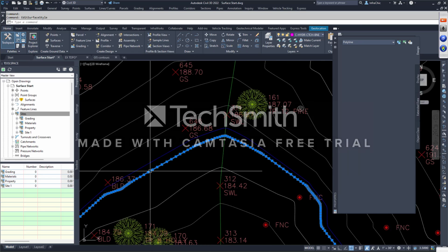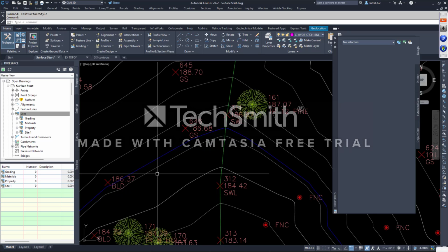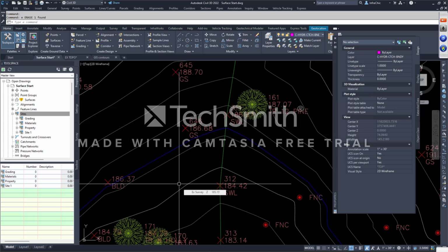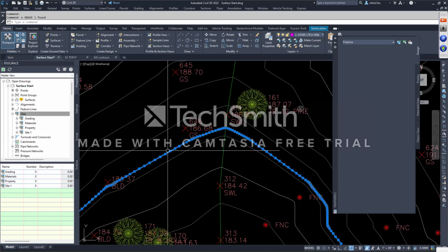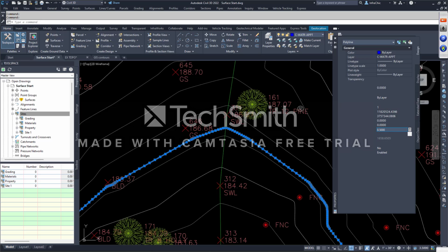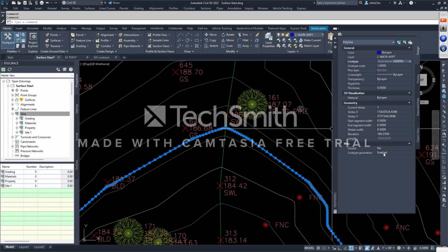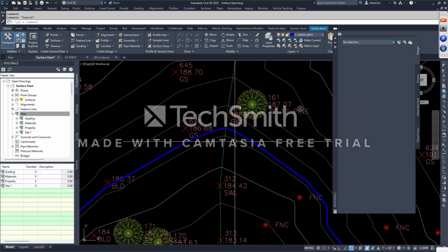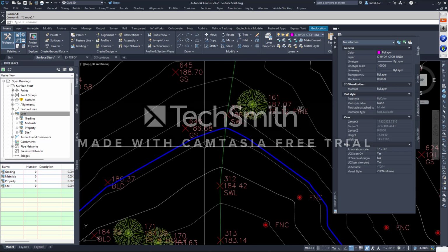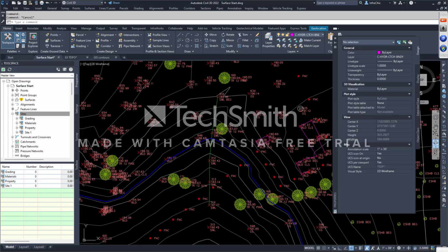And the one I needed wasn't that one. I'm going to erase that one. Now I have my 100-year FEMA floodplain line as a polyline that I can manipulate. I can change its width. I can show it as 0.5, so it's good and thick. I could give it a different line type, everything enabled. So there's a lot of things you can do with extracting objects.